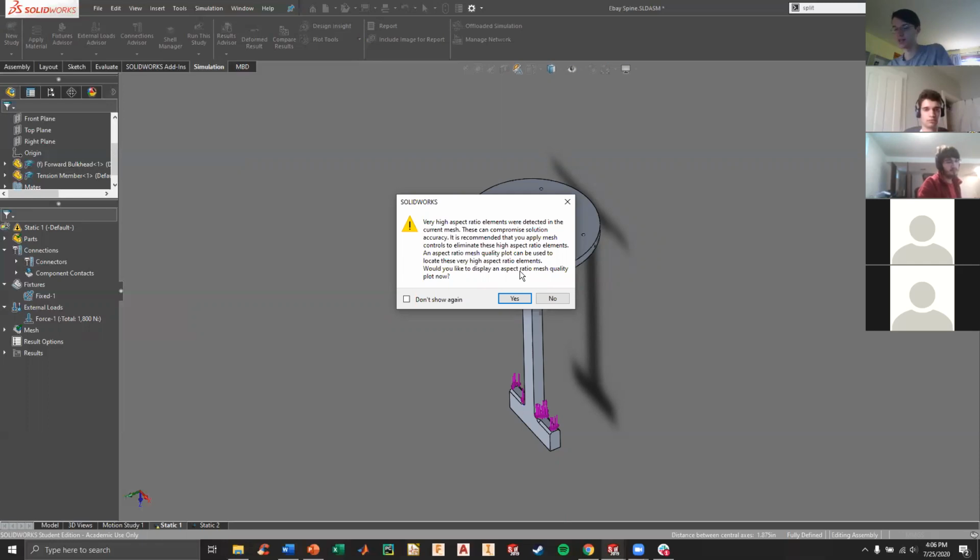So a kind of quirk of how the FEA math works again is that the elements that you want to solve for should be as normally sized as possible. The ideal element is going to be a tetrahedron based on only equilateral triangles. But depending on the geometry you're looking at, oftentimes you're going to have to stretch the element in different ways to get it to fit into the model you're looking at. And when you do that, you're going to lose some accuracy with your parts.